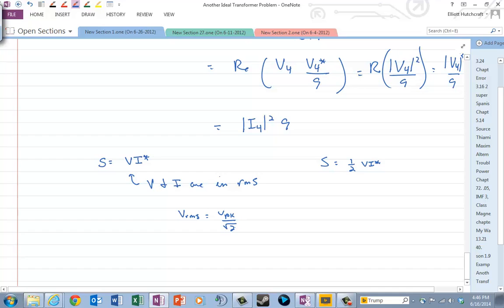Now if you have a triangle wave, half of a sinusoid or a clipped off sinusoid, or a parabolic wave or anything like that, if it's not a sinusoid, you have to go through that integration procedure to find out the RMS value. So it's only really easy to calculate the RMS value for sinusoids and for DC voltages, because the DC voltage value is the same as the RMS value for the DC source.